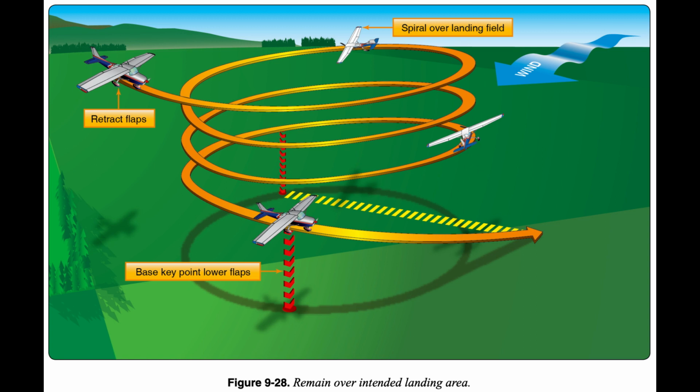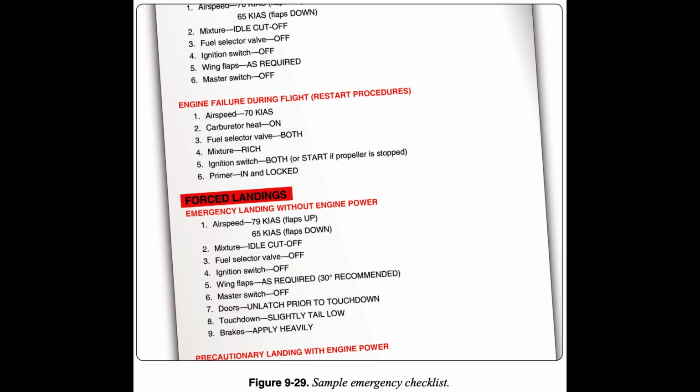Every simulated emergency landing approach is terminated as soon as it can be determined whether or not a safe landing is assured. In no case should it be continued to a point where it creates an undue hazard or an annoyance to persons or property on the ground.